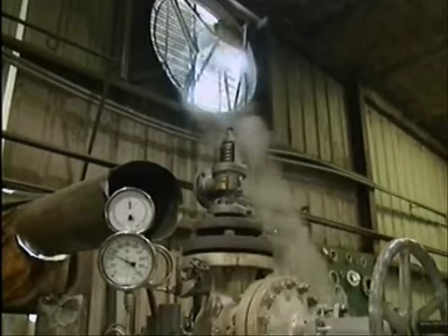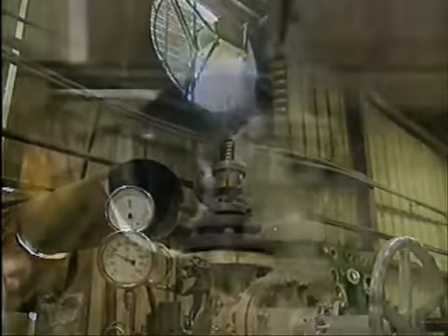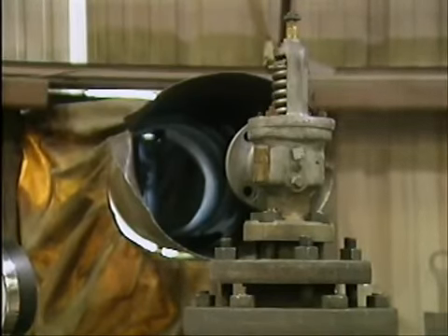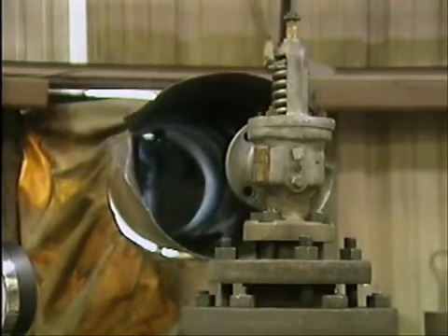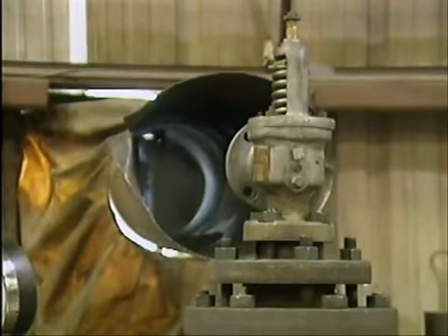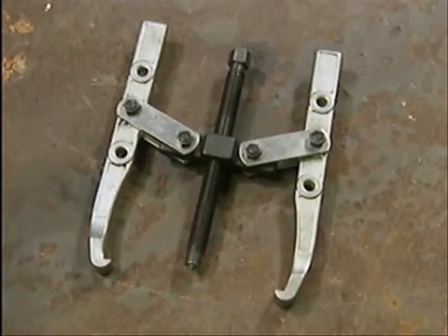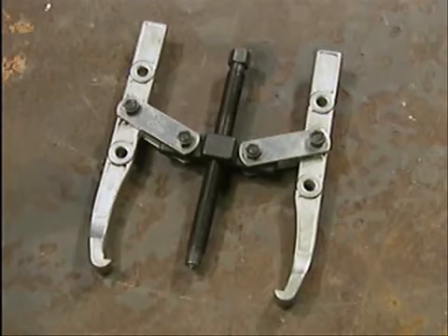Before you can test the valve, you must reinstall it. Take the appropriate safety precautions and follow your facility's procedures to make sure that the installation is done correctly, so you prevent leakage and other problems. Next, prepare to perform the necessary tests. An important preparation for many testing procedures is gagging the valve. Gagging involves installing a device called a gag that keeps the safety valve from opening during testing.